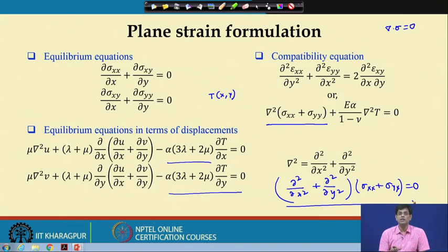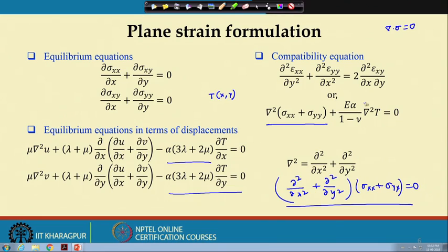Now, if we have the thermoelastic case, if you remember, we were also discussing this compatibility equation when you have an explicit body force in the body. If you remember that, then you can easily derive this, or you can just substitute. This extra term will be there in case of a purely uncoupled thermoelastic deformation.